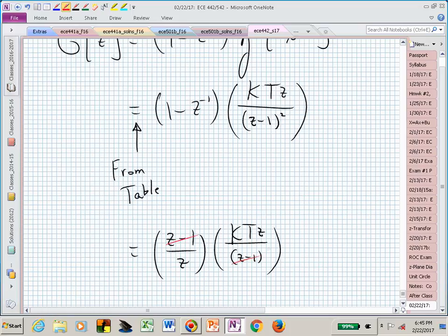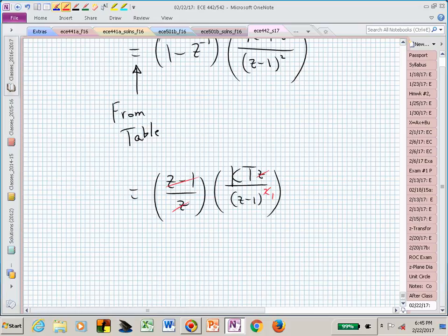So that we now have, whoops, how's that? How about if I do that? Is that better? Right? Are we okay? Now, I need to cancel some more. Now, what's my zero order hold equivalent of a pure integrator? G of Z is now a gain K, the sample period, capital T, all over Z minus 1.